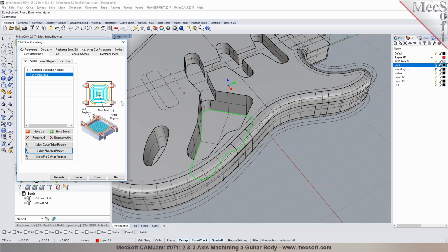That's one step. In 2.5 axis machining, you're fixed at a certain level for each operation. So we did our first pocketing at one level, and then we're going to do the second pocket at the deeper level. What about this other circle that's behind here? That one? That's a separate operation. I'll show you that one too. That's a separate operation, yeah.